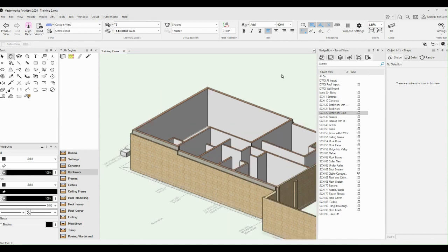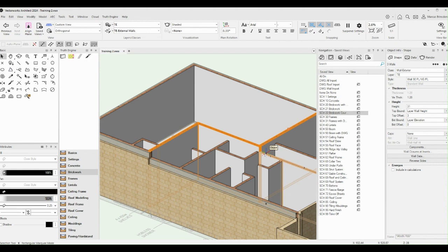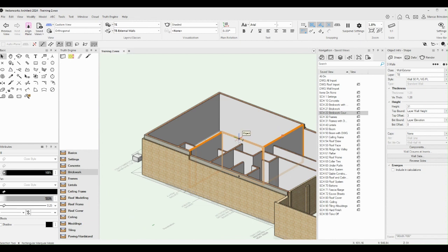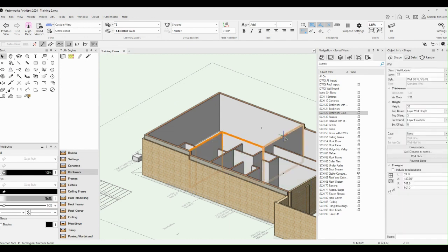Now, these three walls also need to have the plaster drop down 3 courses, as we don't need plaster on the rear side of the wall, so it goes into a 28 course ceiling. So I have a script for that. If you select the 3 walls, so looking at the 3 course area to the rear of the house, we note that these 3 walls don't need plaster on the top 3 courses, so we can turn off or drop the plaster down to the 28 course ceiling level at the rear.